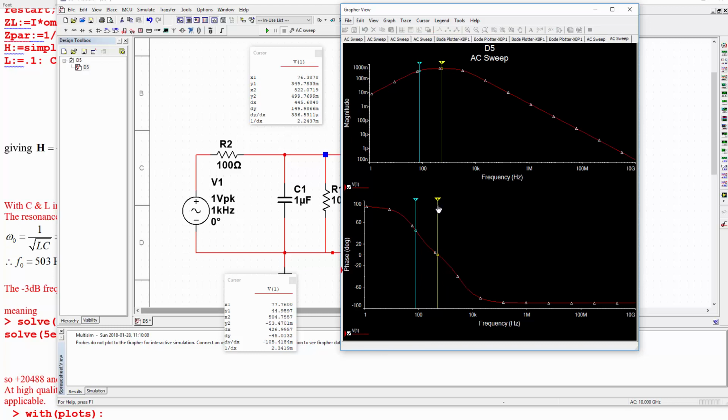Again, it's just pretty hard to drag these into exactly the right range. But this one, I got pretty close. That's at negative 0.05 degree phase shift, and that's at the frequency 505, which is really close to our analytically determined one. So there we go. That's how you use this AC frequency sweep in order to determine the outputs in Multisim.